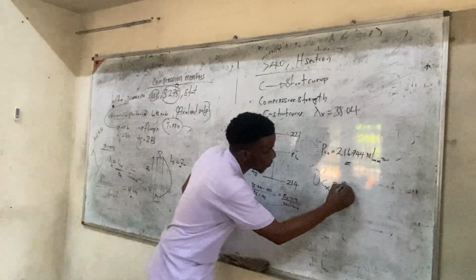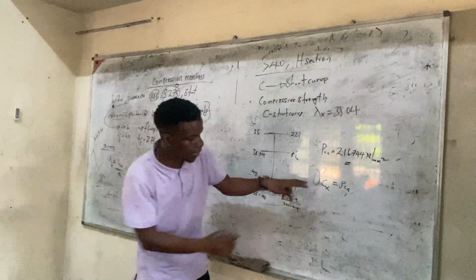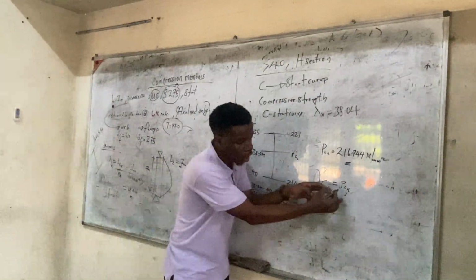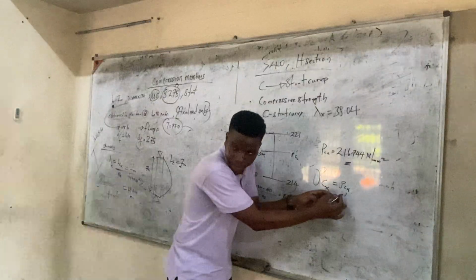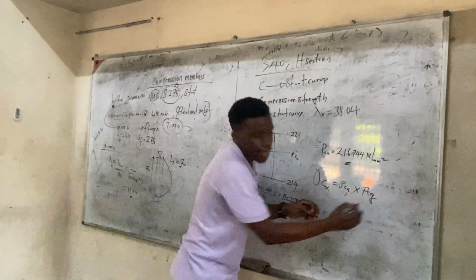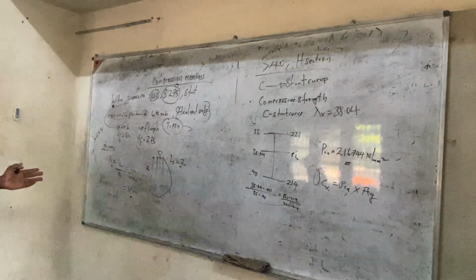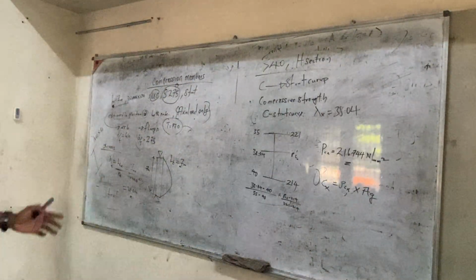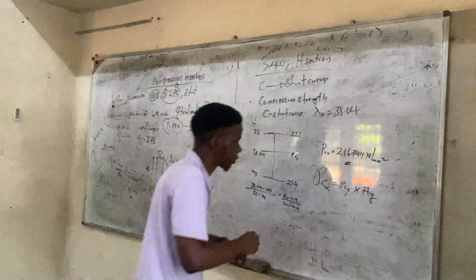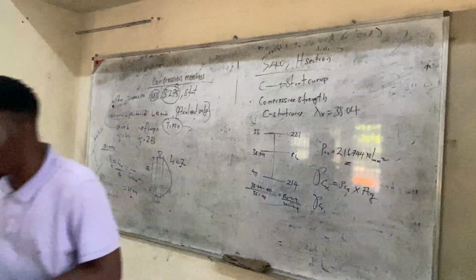So, PCX, small p, big P. Now, the compressive resistance is equal to compressive strength, small p, times AG. I was not even giving you guys the section where it is in the table. But let's just continue first. I think this is 4.7.7.